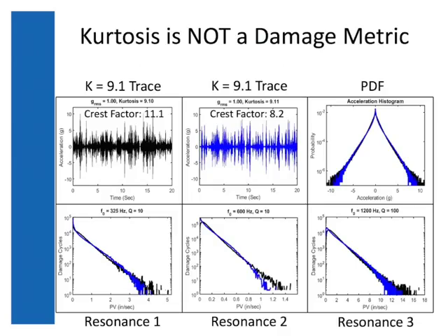There it is. All three of those methods, well, the two shown there and the one on the previous slide, they're legitimate window distributions that we thought about using to generate kurtosis. We selected the blue trace, the one that's on both slides, because we think it's about the same as what we see in literature for other controllers in terms of damage. That doesn't mean it's a good match for kurtotic data you gathered in the field. To get to the second part of the question, for now, we've constructed at least our version of kurtosis so that the damage is not tunable, beyond setting the PSD and the kurtosis value.